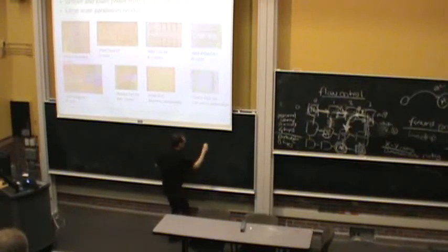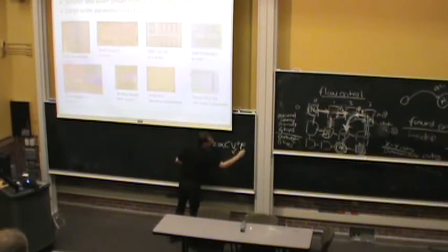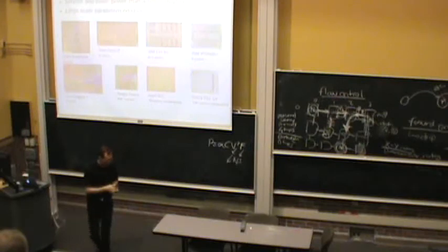I'll just remind you of this instead of C V squared F, right? If you reduce this by n, then your power goes down by n cubed, right? So that's the advantage of putting these cores. And remember, we said that this works well if you can actually parallelize your program, divide it into n, and get perfect parallelization. But we know that that's not true. So these are just some examples, and these are old examples actually. I cannot keep up with the new things. These are Barcelona and Core i7 from a few years before.